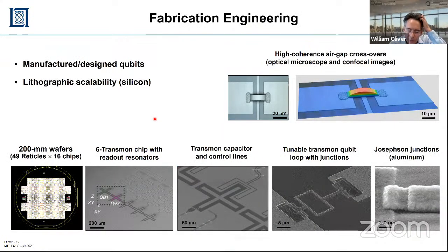Now, of course, we need to engineer and build and manufacture these, and we do that using lithographic techniques that we have from CMOS. And in fact, the etch techniques, the deposition techniques, they're all CMOS compatible. And one other thing to say is that this is a silicon technology. The metals we use, like aluminum, titanium nitride, are compatible with CMOS foundries. And we use silicon wafers, right? And we use the same tool set. So this is absolutely a silicon technology.